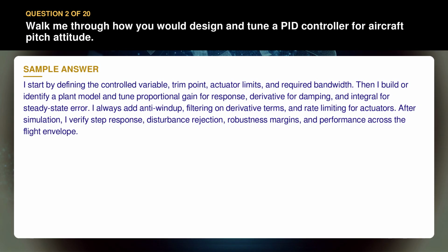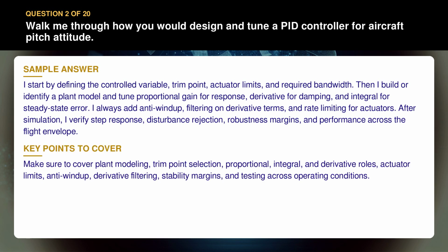After simulation, I verify step response, disturbance rejection, robustness margins, and performance across the flight envelope. Make sure to cover plant modeling, trim point selection, proportional, integral, and derivative roles, actuator limits, anti-windup, derivative filtering, stability margins, and testing across operating conditions.